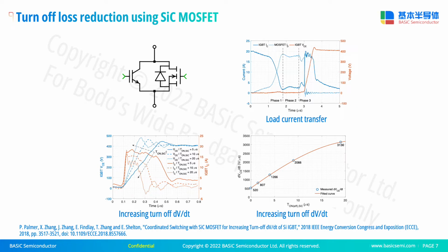Here, as the thermal allowance of the silicon carbide MOSFET in a switching cycle is fully dedicated to switching, the current spec of the silicon carbide MOSFET can be further reduced from existing hybrid solutions to achieve lower device cost. Of course, multiple SOA of the silicon carbide MOSFET require in-depth studies to make sure that such a control scheme is operational.